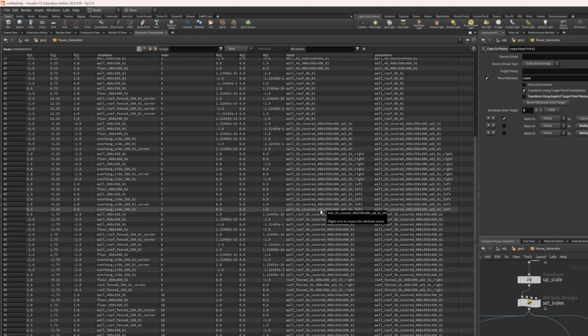So if I was to have a house like this with 82 meshes, and maybe the variety is, I don't know, maybe made of 30 different meshes that instance to make the 83 in this case of the house, that's going to still be 30 draw calls compared to just one for a static mesh.